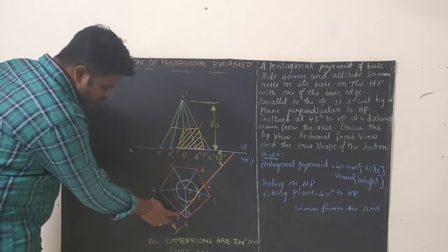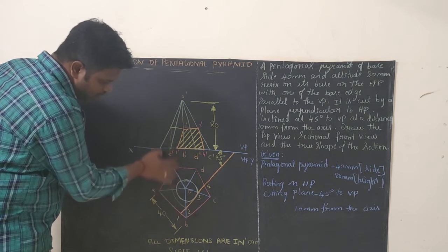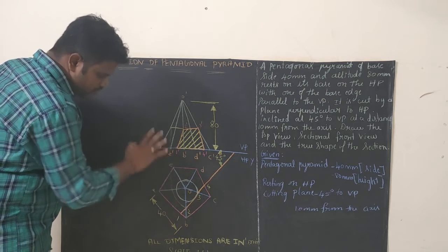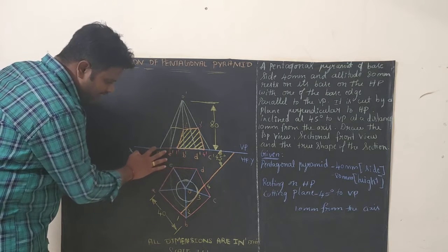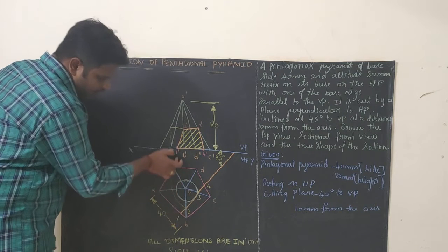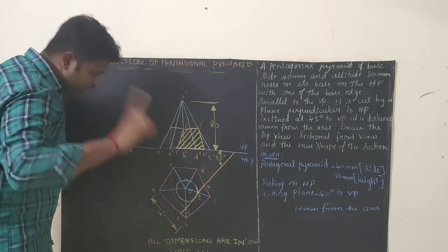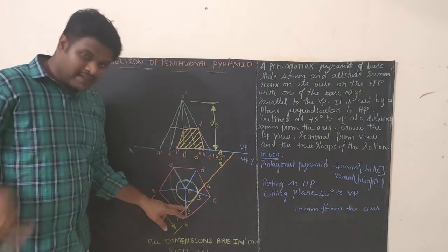Okay, so keep your scale at 1 and keep your scale vertically so that you can extend your line. I haven't drawn the extension line. You can just keep your scale and get a point between A dash and B dash, because 1 is between A and B, which means if you draw a vertical line, it will be meeting A dash B dash at one point. That point is called 1 dash. Next is 2 dash, I will tell later on.